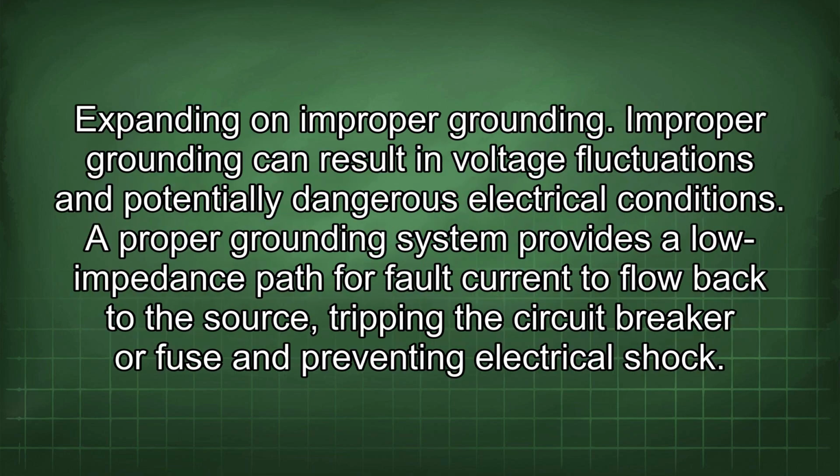Expanding on improper grounding. Improper grounding can result in voltage fluctuations and potentially dangerous electrical conditions. A proper grounding system provides a low impedance path for fault current to flow back to the source, tripping the circuit breaker or fuse and preventing electrical shock.